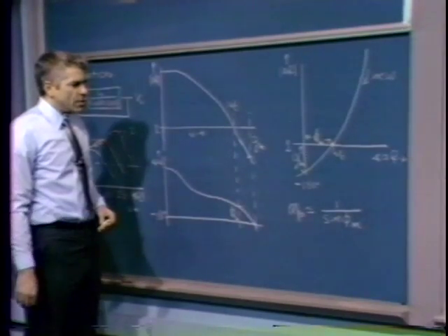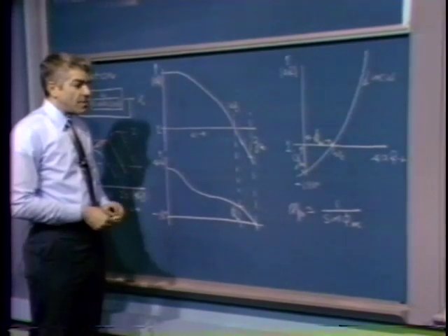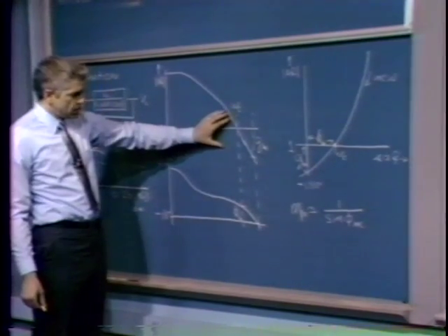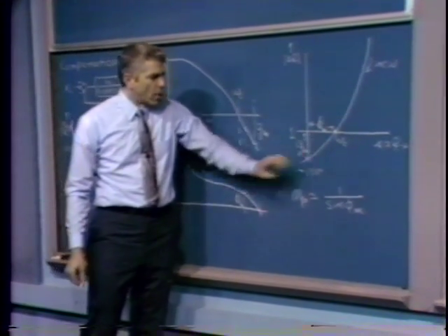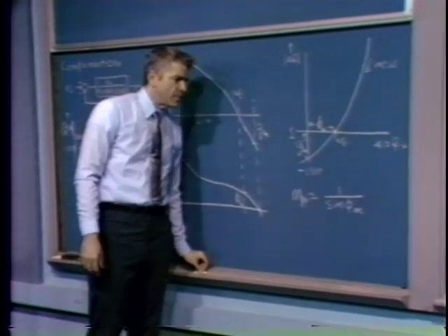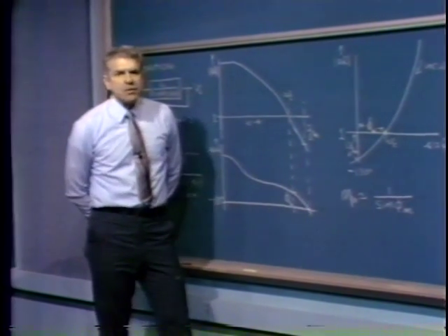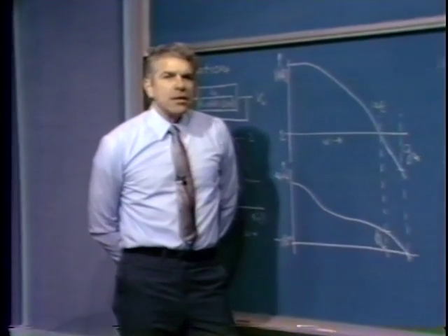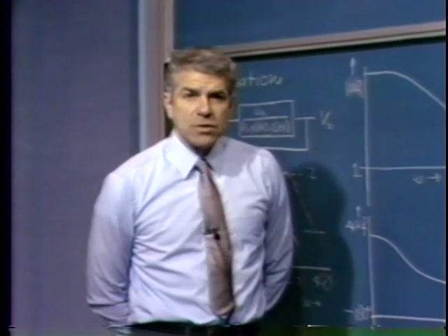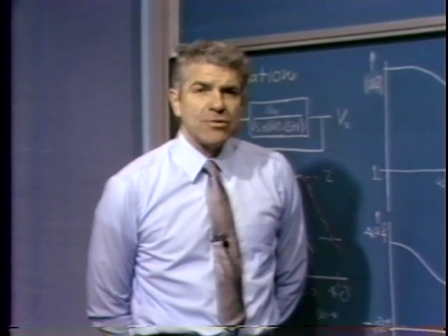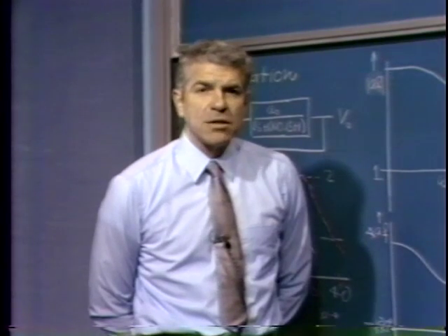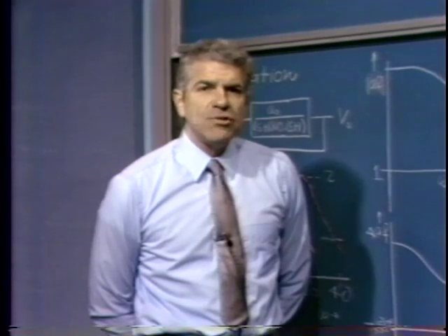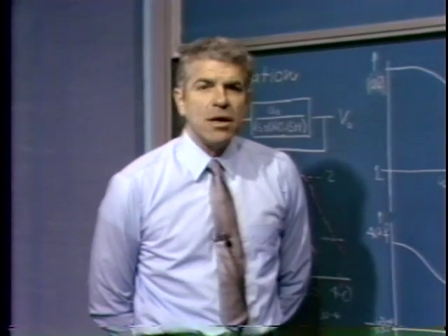So again, we can define the quantities phase margin, gain margin, and crossover frequency in either a Bode plot presentation or a gain phase presentation. Now the value of these quantities is that they very, very accurately predict important features of the closed-loop response of the system. If we assume we have a topology with a frequency-independent feedback path, the one we've been looking at in the Nyquist construction, we can then get a very good indication of important parameters of the system by looking simply at